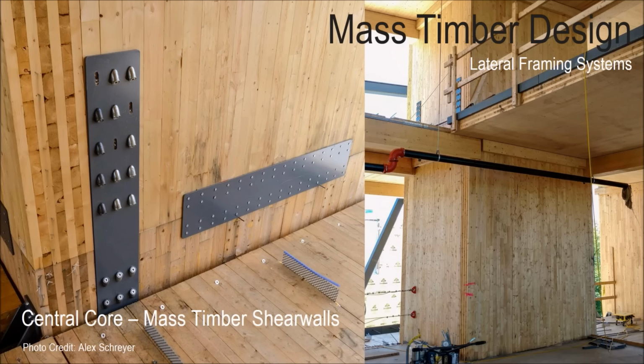So that's ongoing work for CLT shear walls in what you might call the traditional CLT shear wall, because it's hard to call something traditional when it's not adopted in the code yet here in the US. But here's a shear wall that's just screwed and clipped down, as a typical shear wall is to meet code requirements.